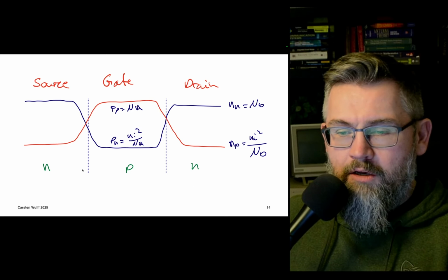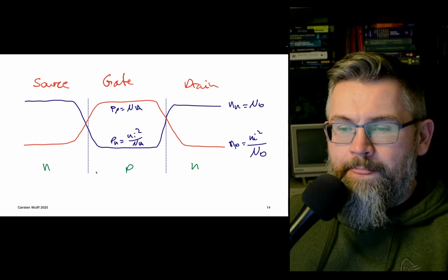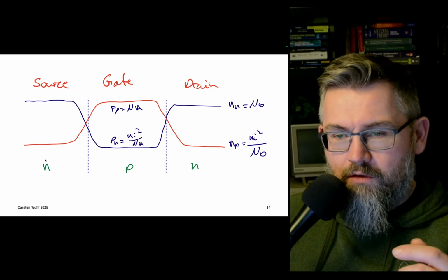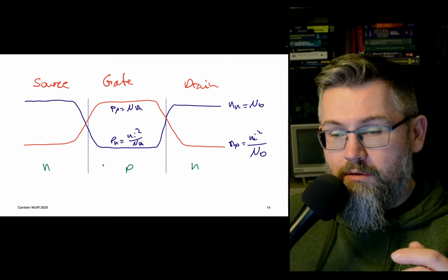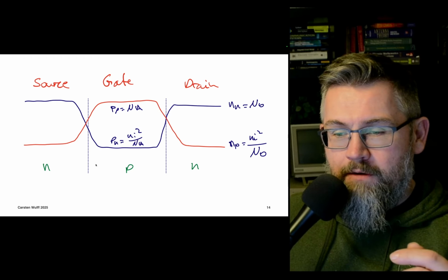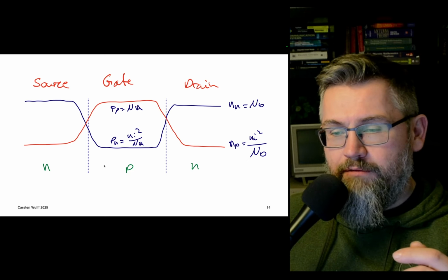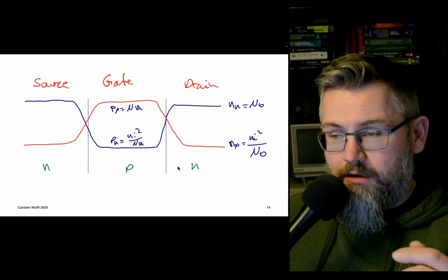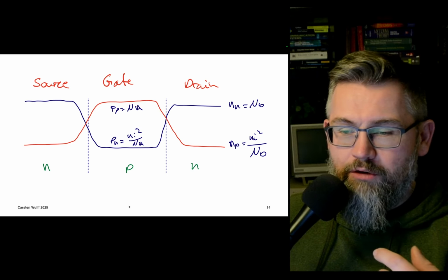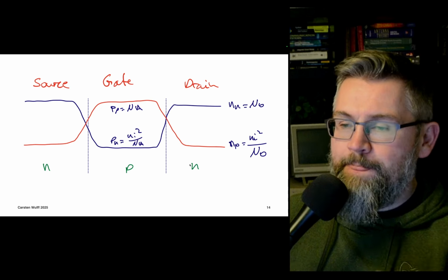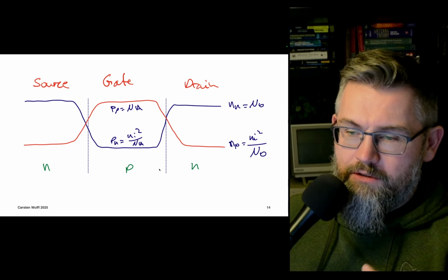This is a PN junction, which means that there will be diodes here. So from the substrate to the source, there's a diode. So the built-in field will be positive on the N side and negative on the P side, and vice versa here. So the diode direction, if you wanted to inject current into the bulk, it would go out the source or out the drain. So there are these parasitic diodes in the MOSFET.